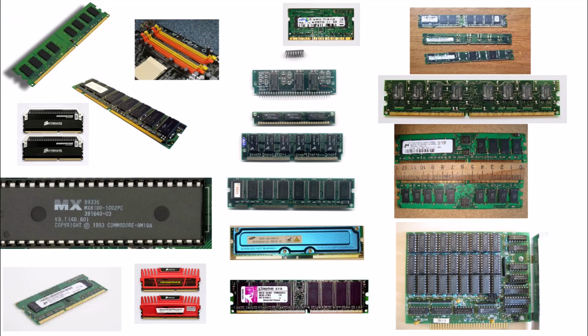Technically, this helped eliminate the possibility of potential damage when mounting the memory chip on the motherboard. RIMM, Rambus Inline Memory Module, is one of the types of computer memory chips, RDRAM. 16-bit RIMMs on motherboards must be installed in pairs, 32-bit RIMMs can be installed individually. Each unused memory slot on a motherboard must be closed with a special cap. RDRAM memory chips are equipped with a heatsink, which is necessary to dissipate excess heat.